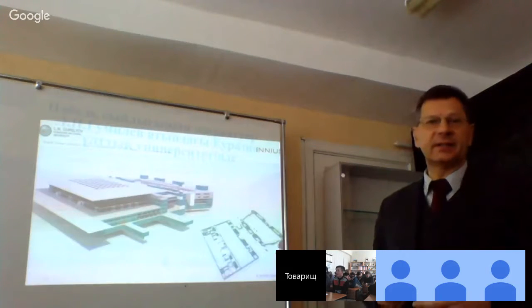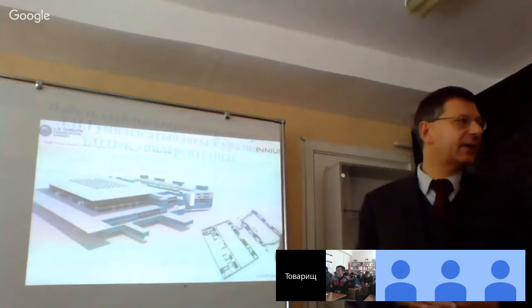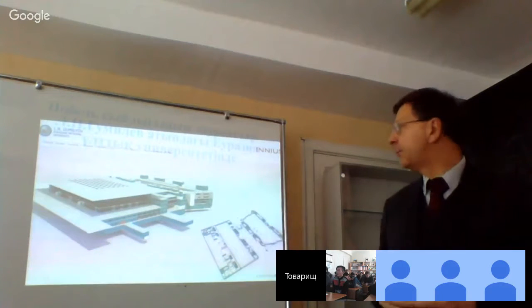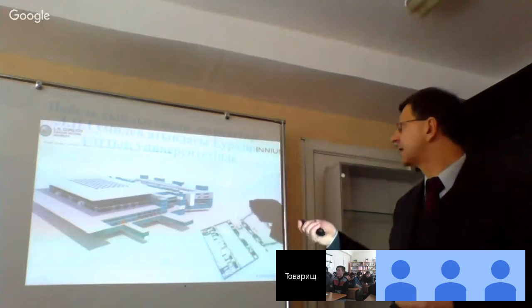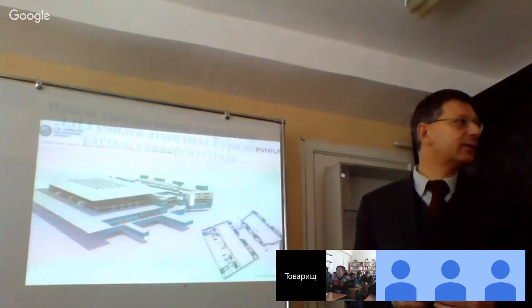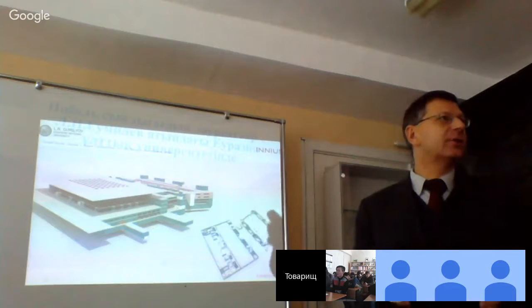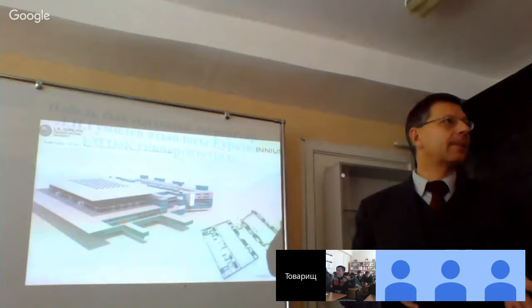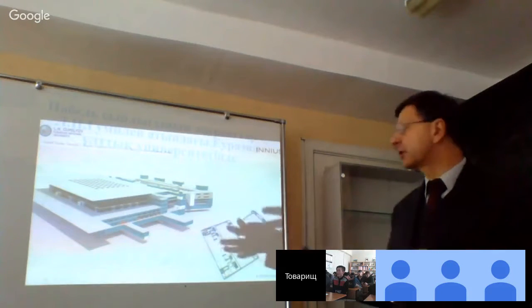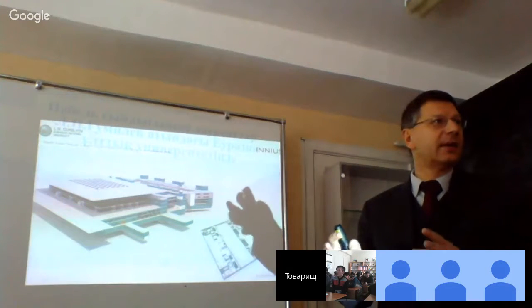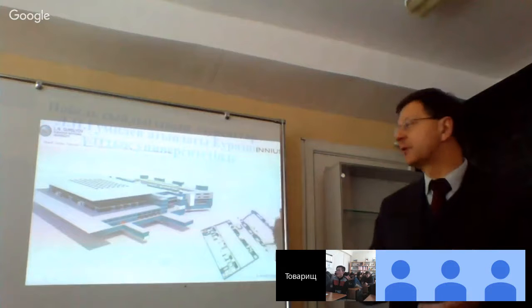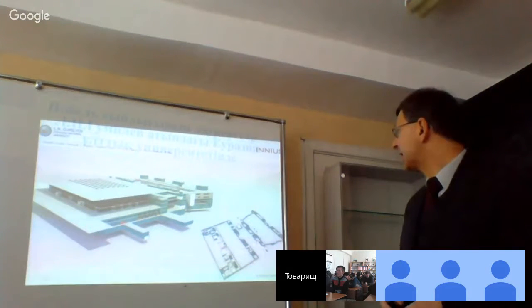And the third is the largest model which we have at the moment. It's part of the new Terminal 3 in Frankfurt. This model has nearly 4,000 rooms, and all the information which we need is in this model. And we transfer this model and the data to the calculation program, and bring the information, the terminal loads, back to the model itself.